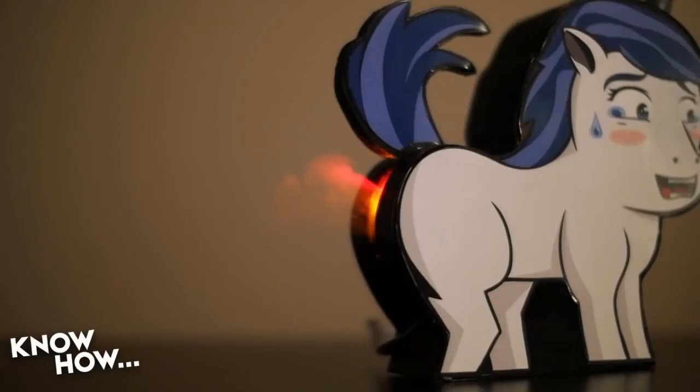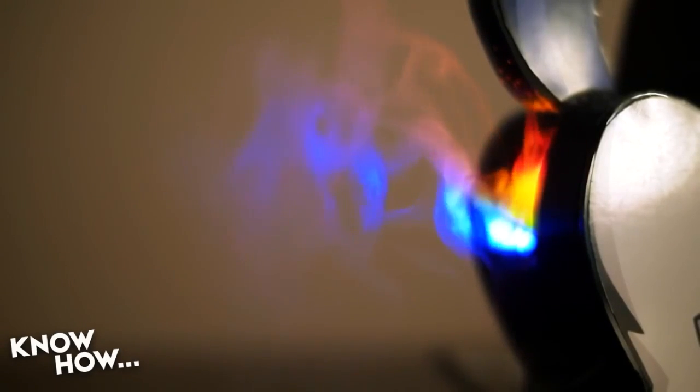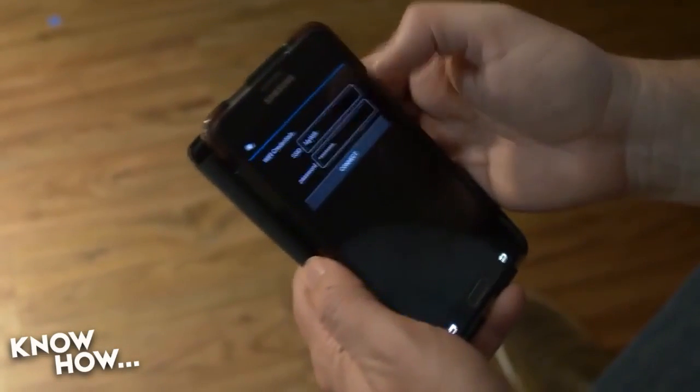The original prototype was an Uno with a Wi-Fi shield and a Bluetooth shield, and the stack became very large, very unwieldy. Also, it consumed more power. We wanted to be able to do what we're doing now with battery power, and some of the production models will actually have a battery inside. So the package in the Intel Edison, especially the mini breakout board with a battery charger on board, was very nice and compact. I also like the XDK. I also like that it's running Node.js, and we use all the communications. We use WebSockets, and I like the fact that I can do that.